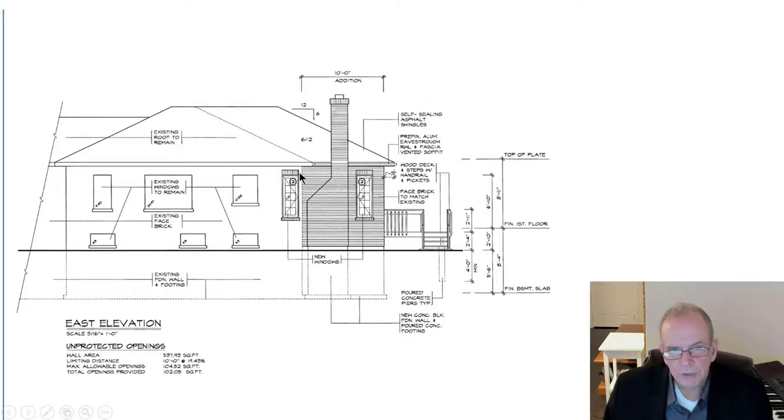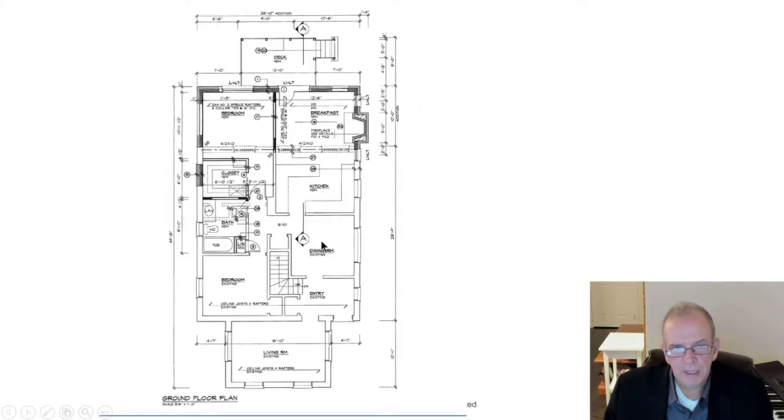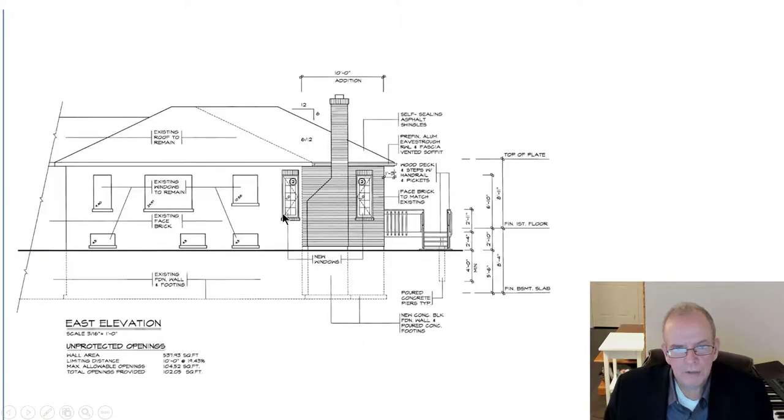There are several ways you could do that. You could cut it out with a saw and then have the window fairly close out to the outside edge, and that might match up reasonably well. The other way is that you could take some of the brick that you took out from the back wall and use that to tooth into this and to use over the top, because there won't be a soldier course over the top. You'll have to put that in.